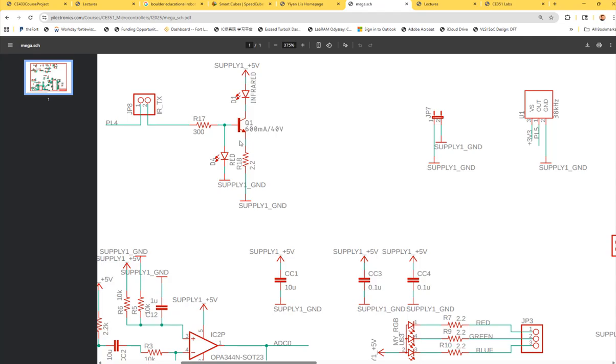It must emit something. If you see signal here, you know the signal passes or is getting passed to this channel. So you know the pulses were delivered to the LED. However, it's still not working. What's the next thing you want to do before you replace any components, assuming the components are very expensive?